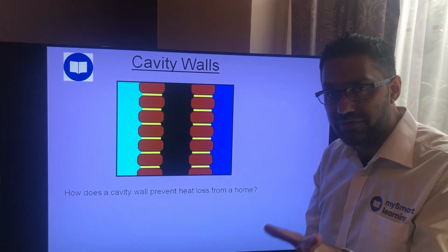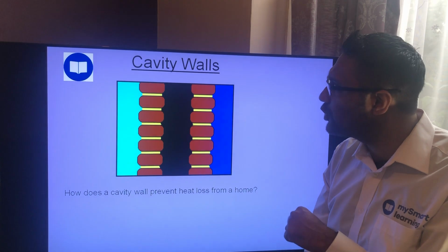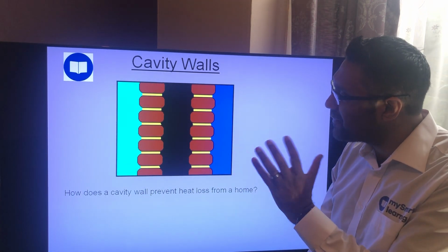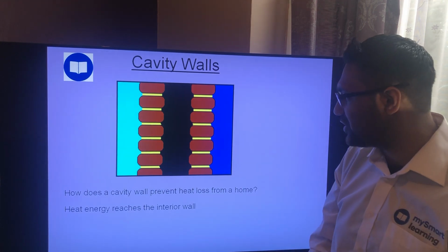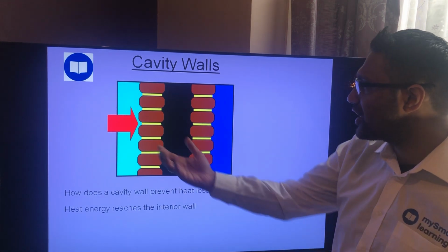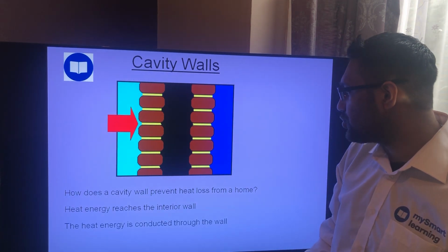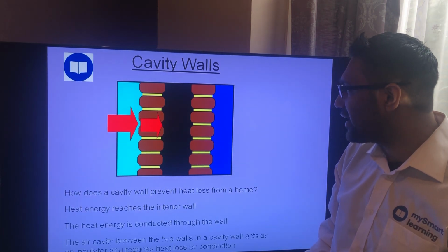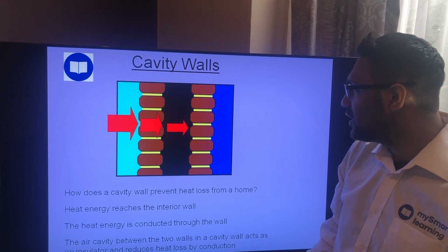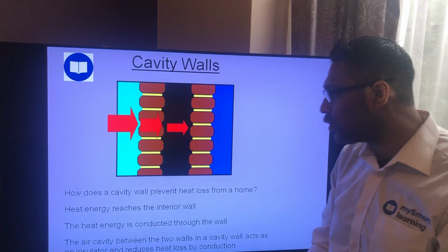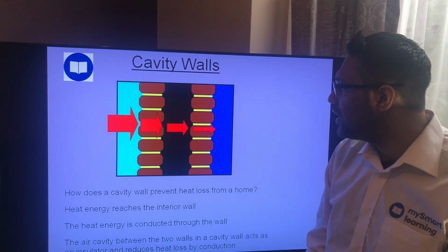But part of the end of this first lesson in topic 2, if you look in the Caboodle book, it talks about insulation and cavity wall insulation. And it's all about reducing conductivity across. Okay, so the way you want to do that, you don't want the heat to escape through the bricks. So you either want to have a gap of air between there, because remember air is a poor conductor, it's a good insulator.